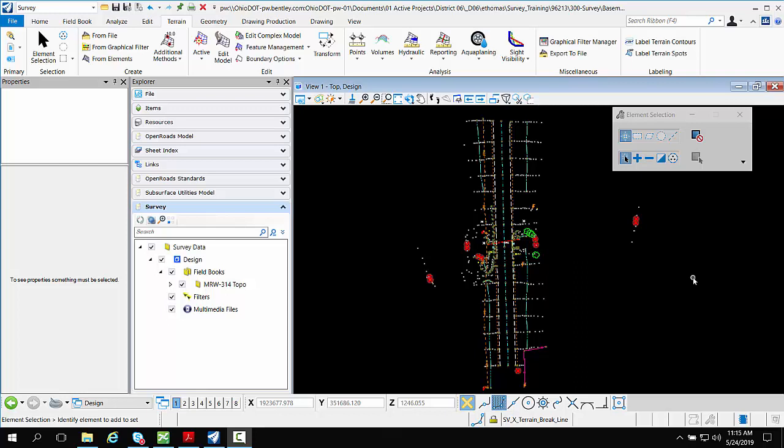The two common edits we see are removing some of the edge triangles and swapping a triangle leg. So I'm going to show you a different method to do that, leaving the survey processing rules active. The reason we want the rules active is if we go back and have to add any additional survey data to this, those rules need to be active in order for it to draw linear features and to make changes to the terrain model itself. So by doing it this way, we can keep those rules active and make the edits a different way.